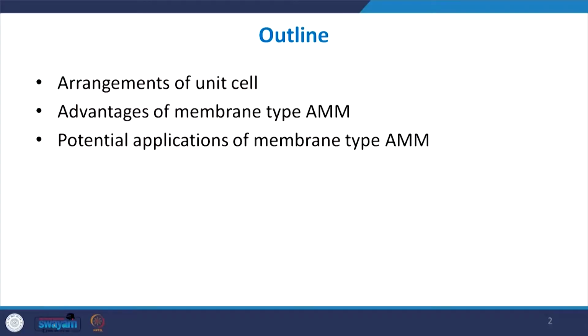So, we studied how, when we have a unit cell with a stretched membrane, it behaves and responds, and how it is able to block the sound. Similarly, we studied the unit cell where you have a stretched membrane with some mass attached to it, how it behaves, and in what regions these unit cells have a negative effective mass density. In that region suddenly these seemingly thin membranes are able to not allow any sound waves to pass through. So, we do not get a propagating wave because rho becomes negative, which means that the propagation vector is negative.